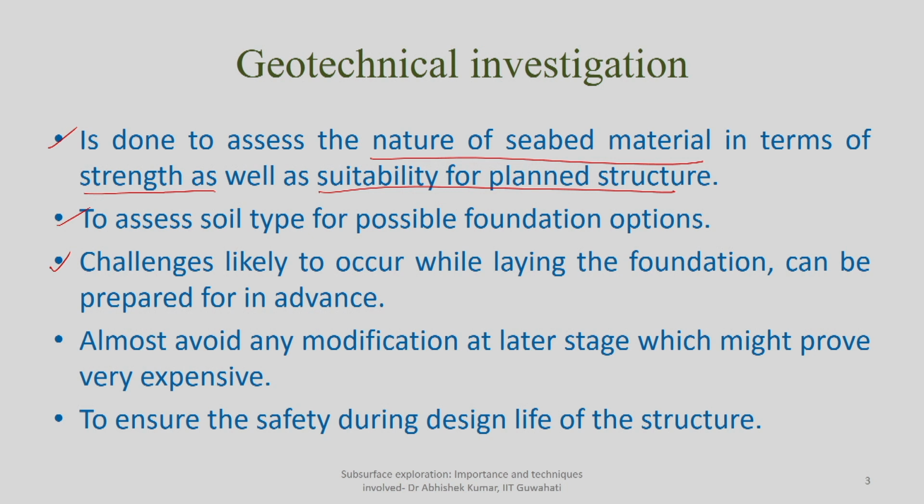If you do not take that into account, you design the foundation based on your geophysical investigation data, but once you start laying the foundation you find some obstacle of foreign material in nature, maybe shipwrecks or something else, which cannot be used as a direct load bearing medium and has to be removed. If that consideration has not been accounted for in your design, that will of course lead to some challenge or difficulty while laying the foundation.